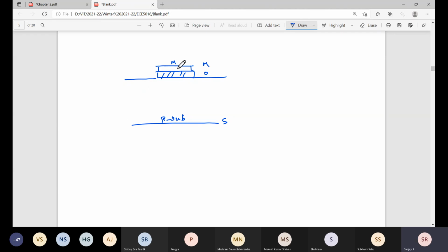So with this, is an inversion layer formed? You remember in device physics, without source and drain only, you studied about the inversion layer. Am I correct? Yes, sir. So the inversion layer is formed. Okay, so if I apply more and more gate voltage, who will supply the electrons for the inversion layer? Either from the substrate or from source and drain? Substrate.